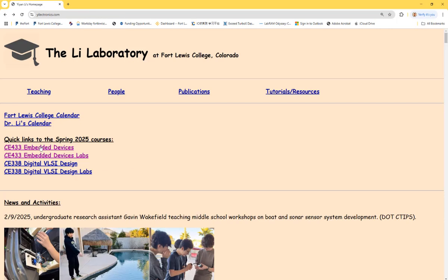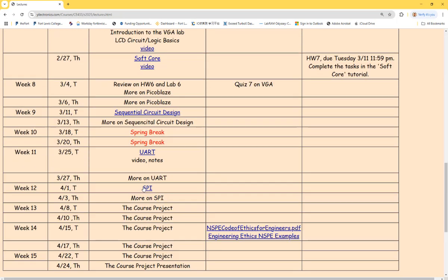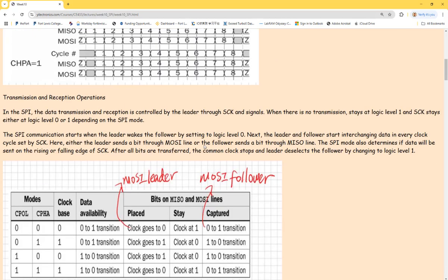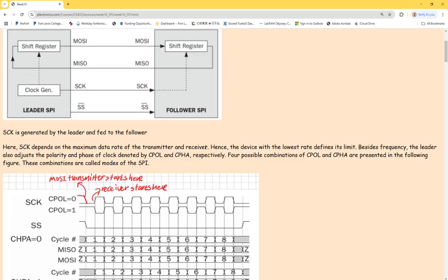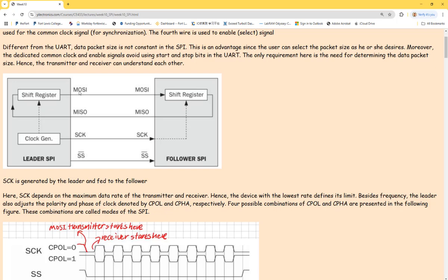So if you look at the SPI here, probably you have used a lot of sensors, digital sensors that have a SPI port. Okay, so all these input and output, clock and enable pins. You can search for any sensors that have a SPI communication port and interface with your FPGA and do some meaningful applications. It could be something similar to what you have done in the past, like CO2 sensors or air quality detection. But let's use the FPGA to do it.